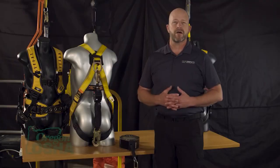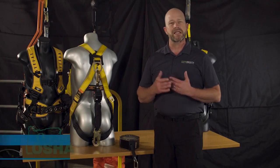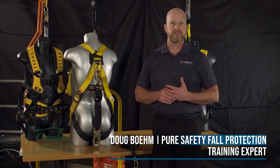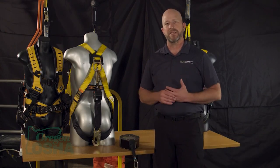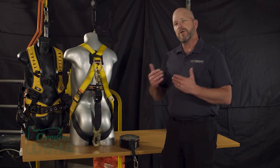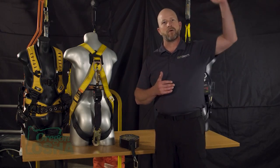Another version of SRL that you're hearing commonly in the market is that of an SRL LE. LE stands for leading edge. Now that's a specifically designed piece of equipment because, again, same thing as with the lanyard connecting devices, we don't always have an anchorage that is here or above.